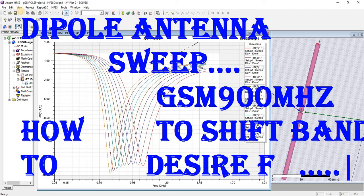In part 1, we have designed a dipole antenna. Now we are going to add the sweep in the result of the dipole antenna for the application of GSM 900 MHz frequency, and we will shift from 0.9 GHz to 1 GHz, and we will see how we can shift this resonance frequency to 0.85 GHz to 0.8 GHz.